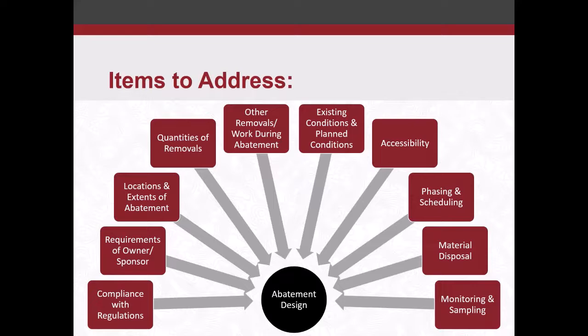Not so much what the contractor has to do. They're not providing the monitoring and sampling, but they have to be aware of that being done, and what there might be for time frames for sampling analysis. The contractor is going to want to get in, get their work done, and get out, but they've got to be aware that it'll take a day or two to get certain samples back from the labs. So specify that up front, and everyone's aware of it, and it makes things go a lot smoother.